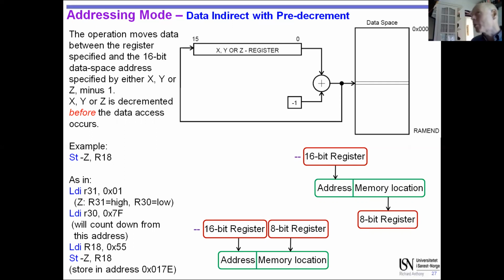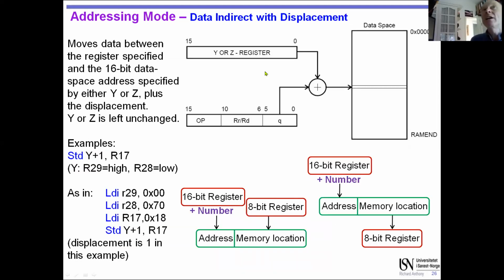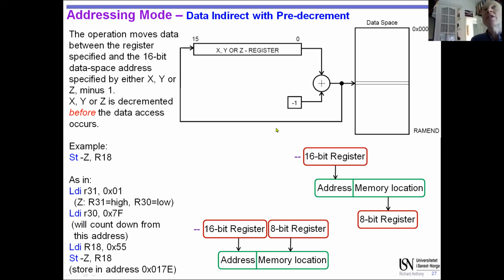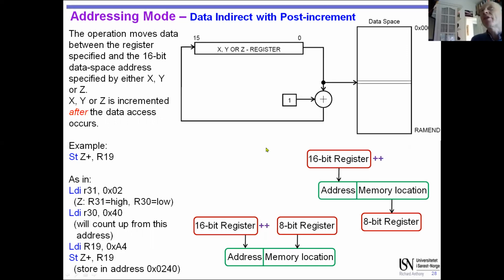The less code you write, by the way, the less code you have to test. So removing instructions is good for you, but in terms of runtime, it's also a little bit faster because it's saving you a clock cycle. This is quite powerful, especially if you've got a loop that's going to run 1,000,000 times, since this would save 1,000,000 clock cycles. So this is an optimization of the previous. As long as you understand that, this becomes an obvious extension. And they can do this with a very small cost in terms of silicon. It's like, why do you climb a mountain? Because it's there. But actually, this is quite useful as well.